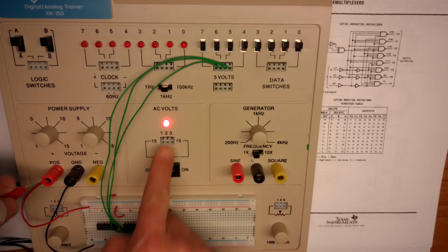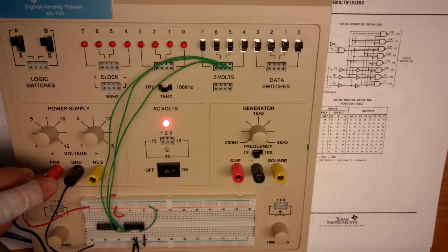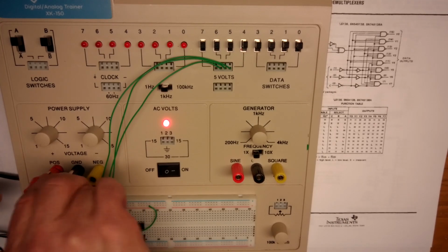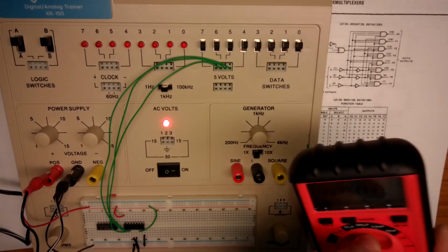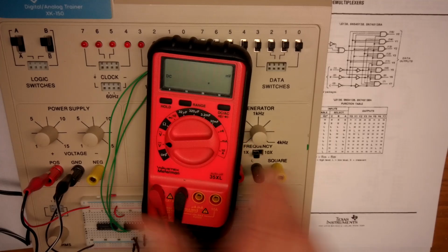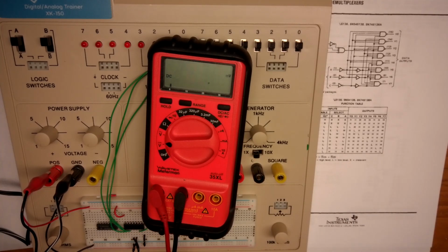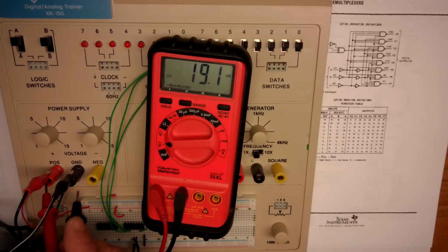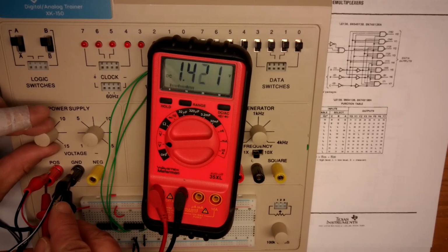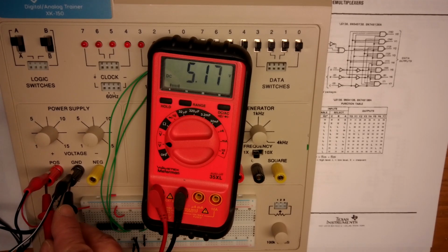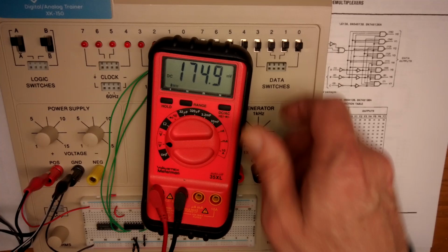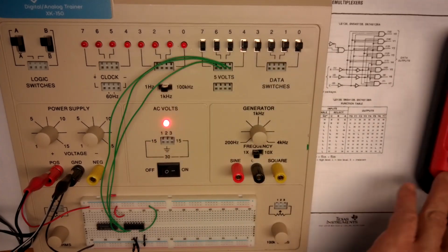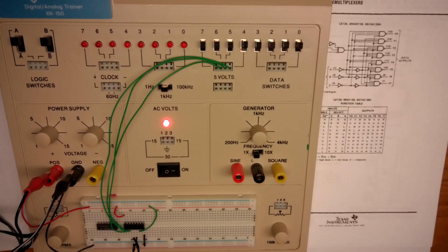So I'm going to turn power on, my light stays on, and it's good. I'll go ahead and drop my logic probe here, but I also need to set my voltage to 5 volts, so we'll go ahead and do that. So get down here, turn this up to 5. Again, be careful with these voltages. If you were doing something else on here that had a 9 or 10 volt, you're not going to want to leave it there very long, because these digital ICs aren't going to stand up to it long.